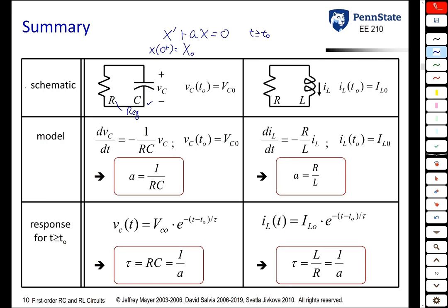And we're going to see that you have initial voltage across the capacitor, Vc naught. Likewise, in an RL circuit, you can always model it as an inductor in parallel with a Thevenin equivalent resistance, once again with an initial current through the inductor of IL naught. These two values come from DC steady state before